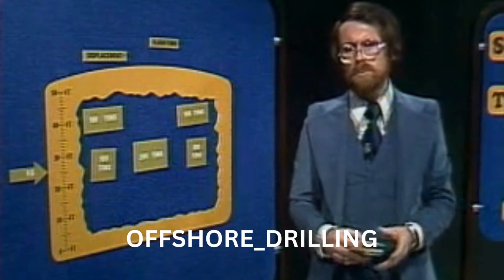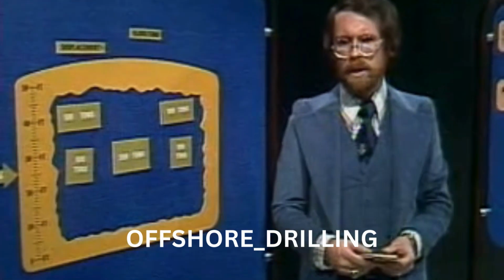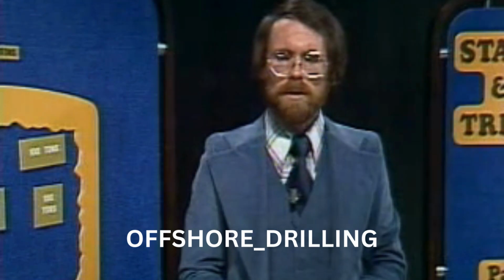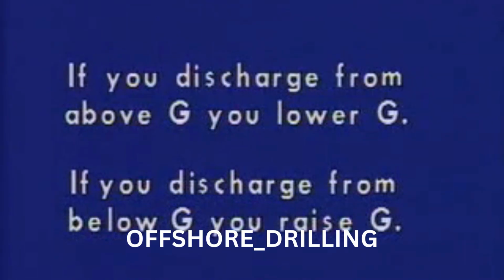If we look back at these two problems, we should be able to make a few rules which will show the effect on G when we load or unload cargo. First, if we load above G, we're going to raise G. Second, if we load cargo below G, we're going to lower G. And third, if we unload cargo from above G, we're going to lower G. Finally, if we unload cargo from below G, we're going to raise G.